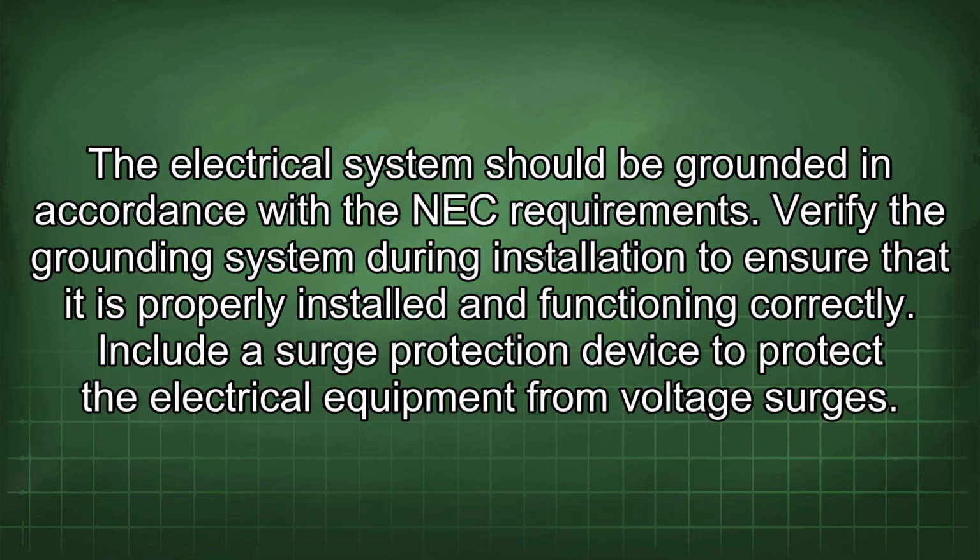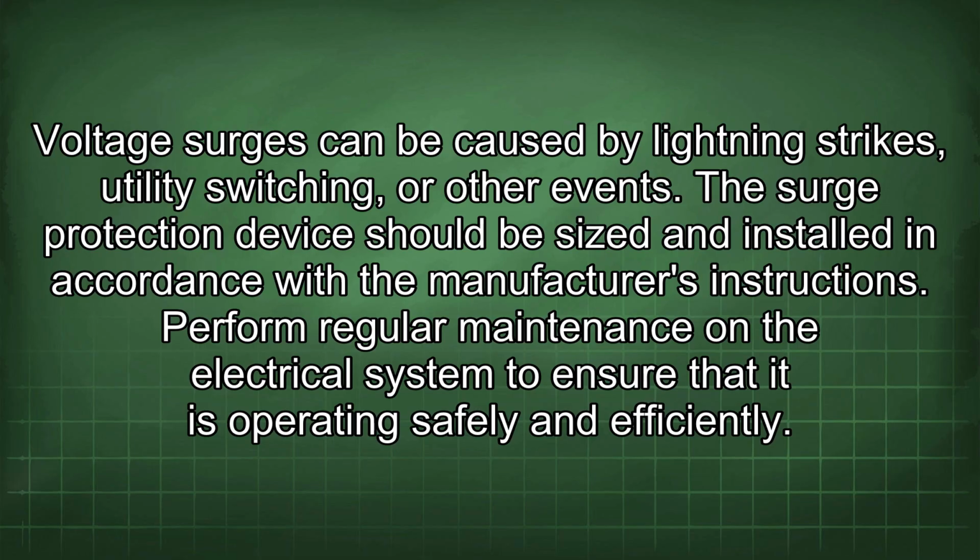Include a surge protection device to protect the electrical equipment from voltage surges. Voltage surges can be caused by lightning strikes, utility switching, or other events. The surge protection device should be sized and installed in accordance with the manufacturer's instructions.